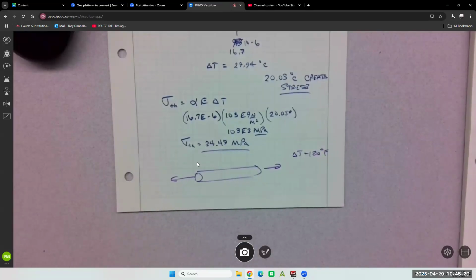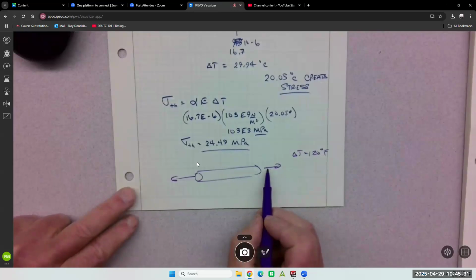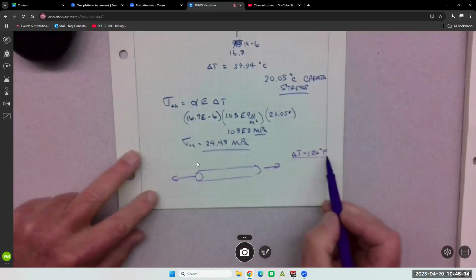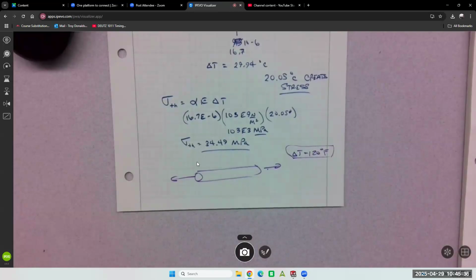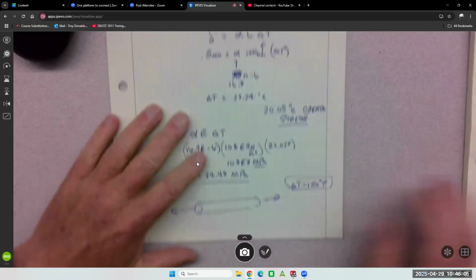It's going to expand due to this load, and then it's going to expand some more due to the temperature rise. I would not do the temperature after; I'd use the original length, because if you did the temperature after the load, the thing would be longer. Everything gets installed at an average temperature and then things happen to it: loads, temperature. All right, good.